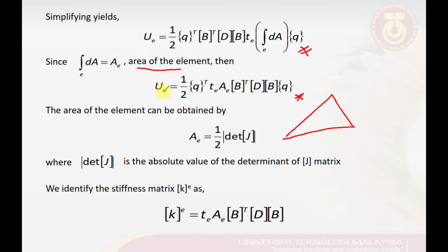Then if we solve this internal strain energy, we can obtain the stiffness matrix for our CST element, which is given by these expressions.